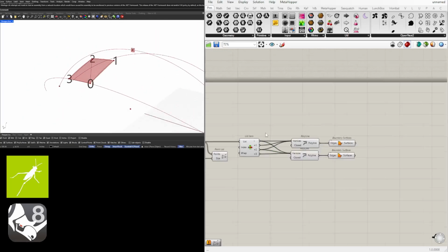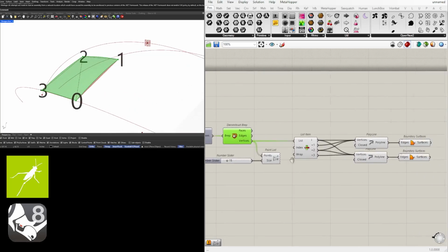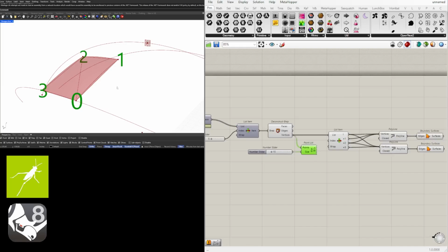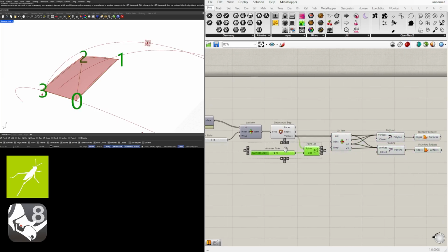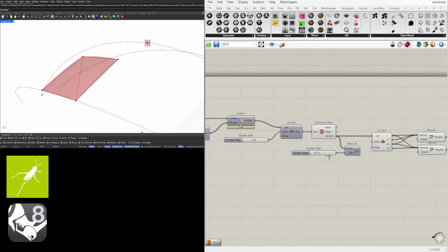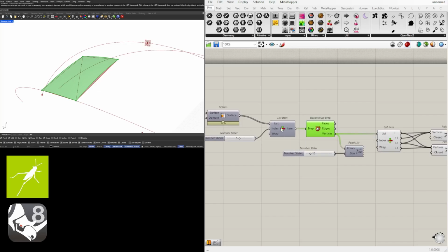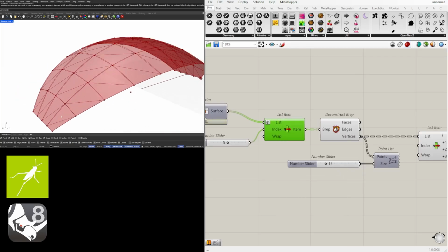All we did was take these vertices that create a square, subdivided them between the points that there are, and then created these triangulated polylines. That's why we use this point list, because it shows us how they're organized and lets us use List Item to create these triangles. So now we can take this and hide it because we don't necessarily need it. And like I said earlier, if we do it to one, we could do it to all. So here we picked just this one item. Now we can go here to Graft. Now it's going to create a triangulation for all of them.